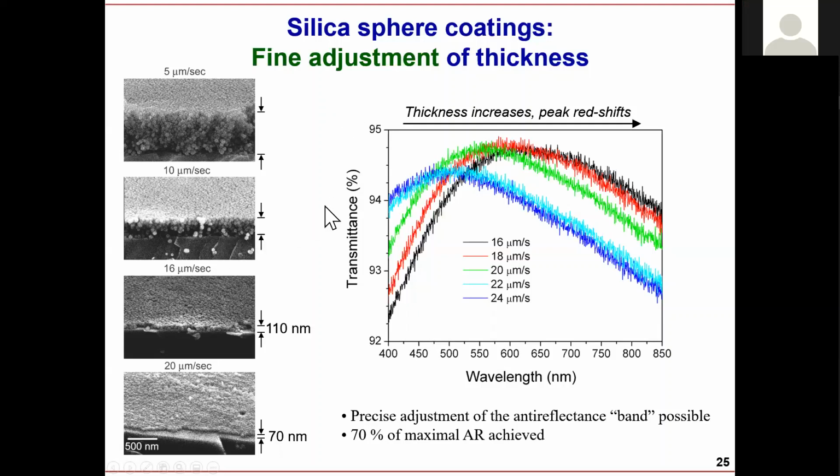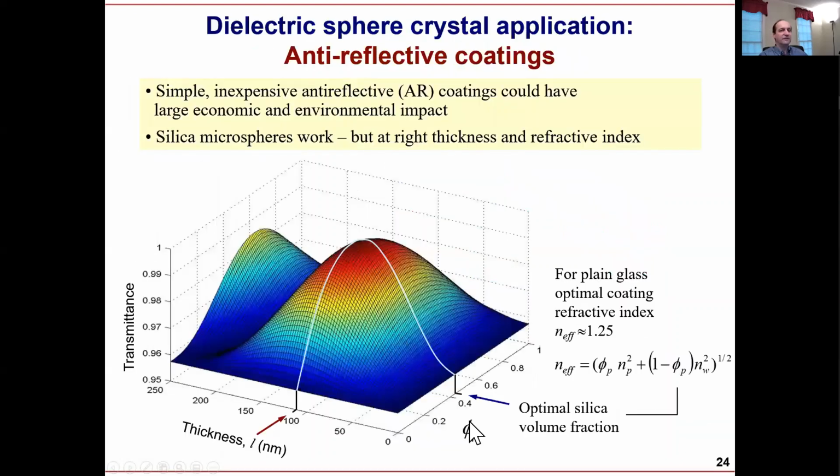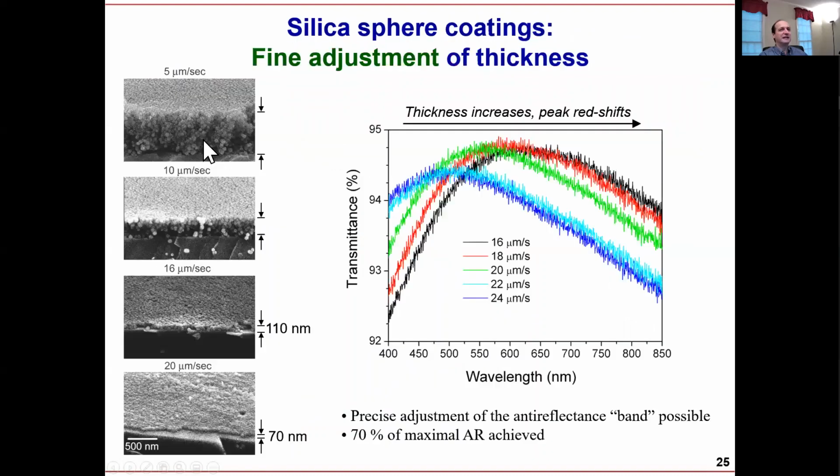Any suggestion before we show the 3 solutions on the next slide? You maintain the same thickness, right? So the thickness you control, right? So right now, you need to control the refractive index. That is, if you take a look here, volume fraction. You need to control the volume fraction of the particles in that coating. How can you do that? The size of the particles? With smaller particles have tighter packing? I do not agree too much with that statement, Austin, because packing of spheres is always the same, right? Regardless of the size of the sphere.